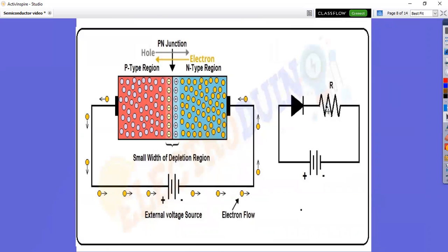If we form a current loop through a diode, resistor and a battery, we can get current to flow in one direction. So one particular use of diodes is in rectification power supplies, where we want to convert mains AC to low voltage DC power supplies.